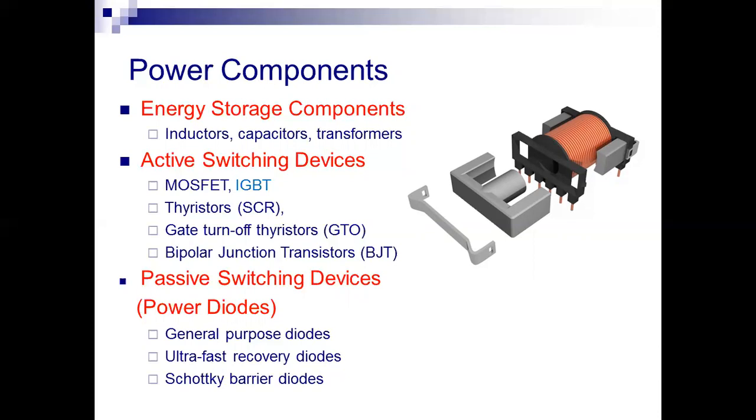Here, these switches work at a rated voltage of greater than 1000 volts, not just greater than 24 volts, with ratings of thousands of volts and thousands of amperes. The MOSFET, IGBT switches, BJTs and also thyristors, also called a silicon controlled rectifier, are used in converters.